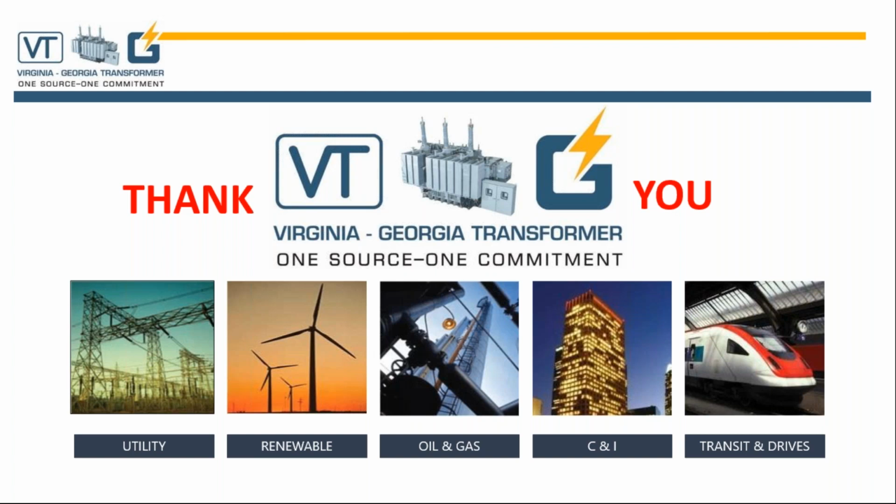Very good. I have one other question. What is the impact of reverse power flow for a transformer operating in the field? So as was explained in detail by you, the first thing is that the voltage is going to increase, and you said it is 15%, and we don't know whether it is 15 or 10 or 20%, and the impact of that will be determined by your own design and the flux density of the transformer which is operating. Like I was explaining, if it is already designed lower, then we may not see any issue, and if it is designed at higher flux density, then you will see all the issues. Very good. Any other questions?